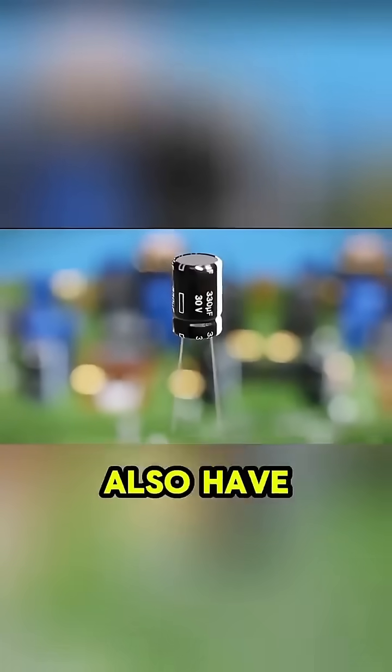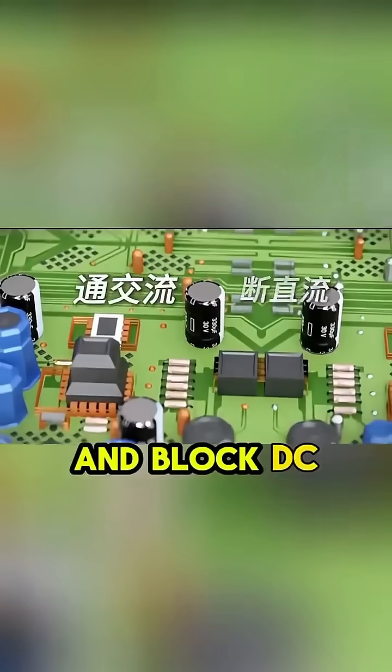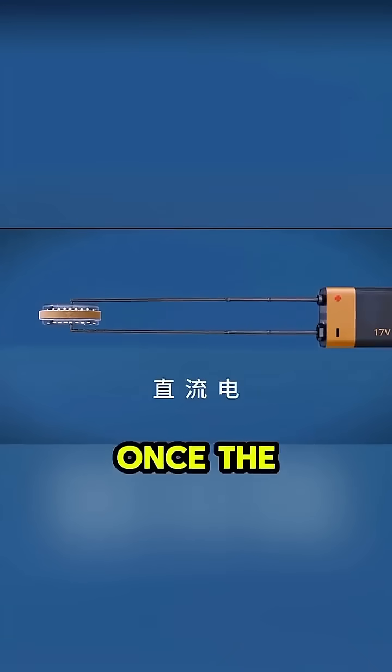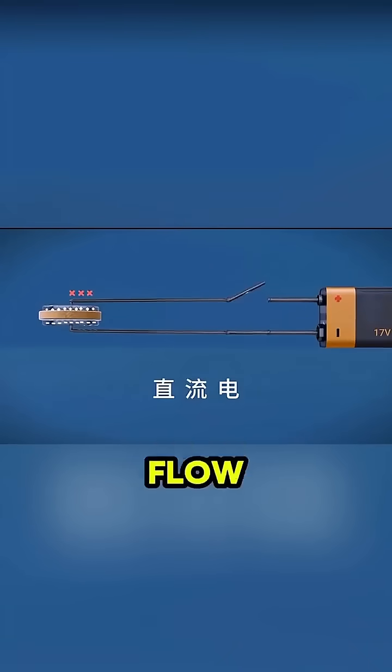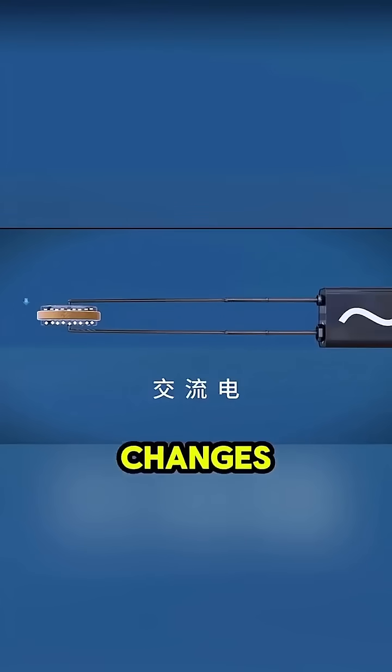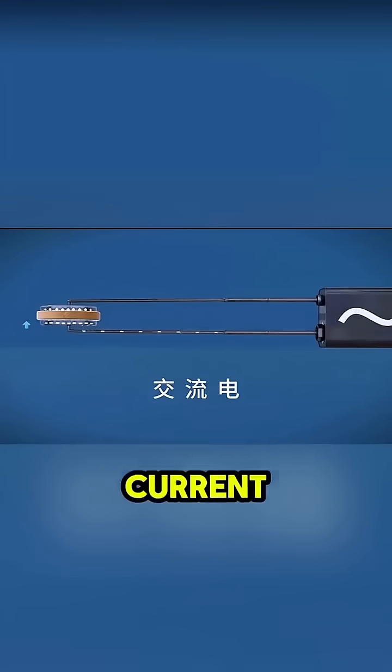Besides that, capacitors also have the function to pass AC and block DC. In a DC circuit, the insulator's barrier means that once the capacitor is charged, no more current will flow. But when the power is switched to AC, the current's direction constantly changes. Therefore, the circuit can still conduct current.